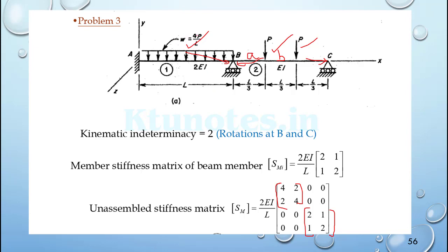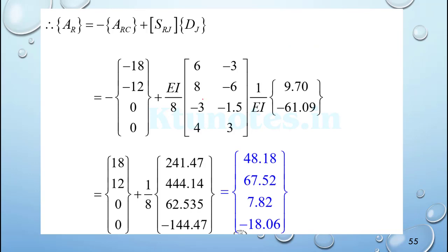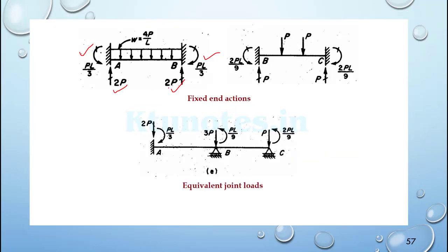because the total load is 4P by L into L, which gives you the cancellation, and then 4P as the total load by 2 will be 2P reaction. And for here, total P plus P is the total load, so P on both supports. The moments are WL squared by 12 for here, and the corresponding equations are referred, because for the center it is WL by 8. For the P you have to find WA square B by L square and WAB square by L square.